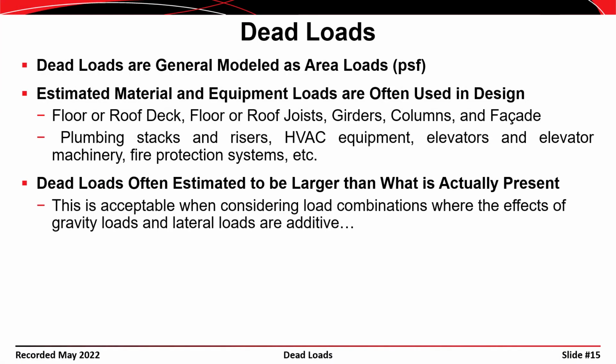Okay, dead loads are often estimated to be larger than what is actually present. At first, this doesn't seem like a bad idea. If you think you're going to get 84 pounds per square foot and you design for, say, 150 pounds per square foot, you might walk away thinking that you were being conservative.